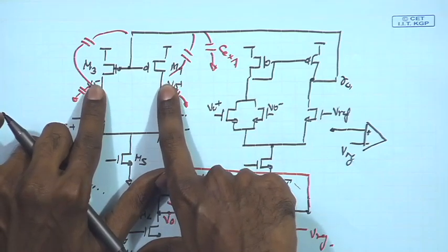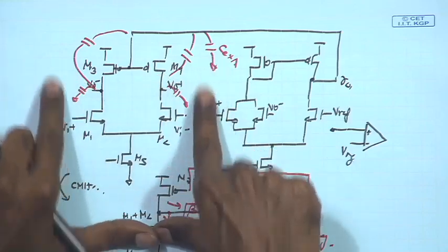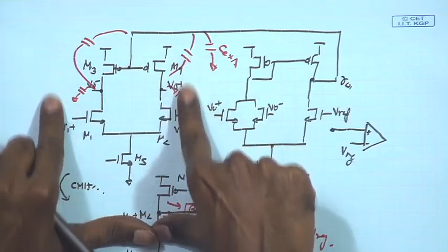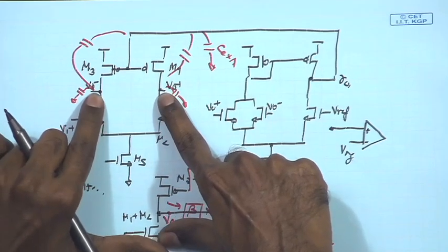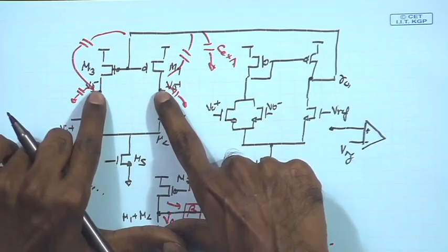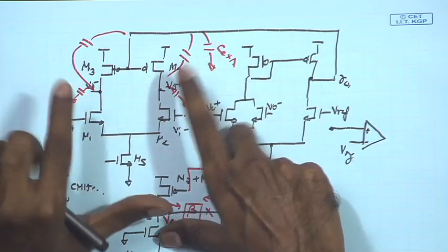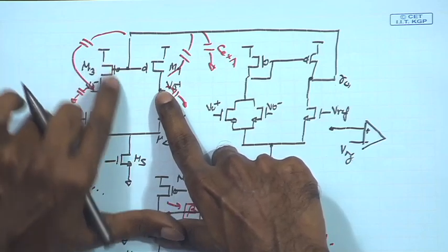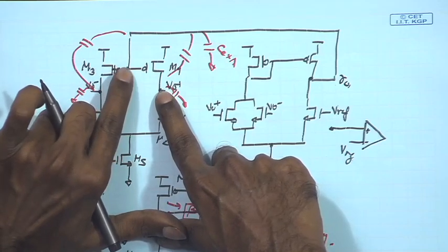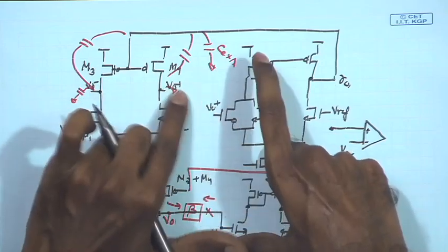So, for example, even if you have a 2-stage amplifier, yesterday we did a common source amplifier, we put 2 common source amplifiers over here. In the simulation exercises also we will look at that the DC bias point over here for achieving the best possible swing at the output will be relatively high, close to the Vg of this MOSFET. And after that if you have a common drain, it will have another VGS drop.